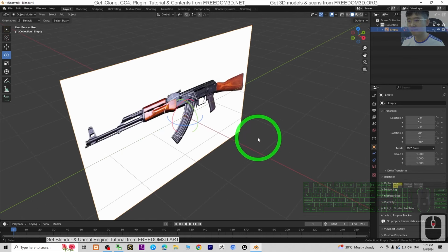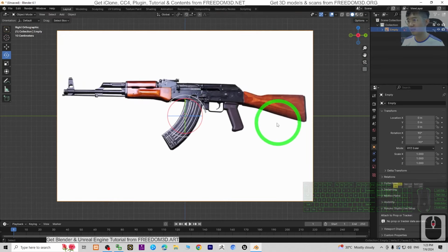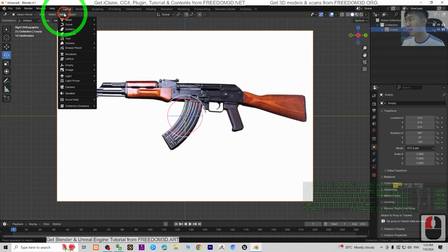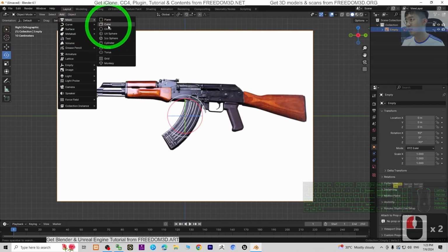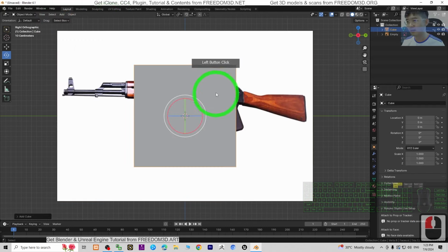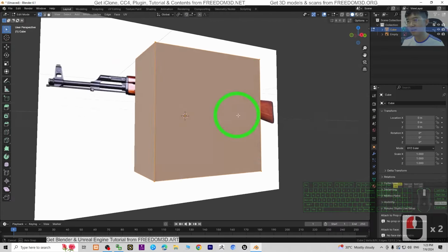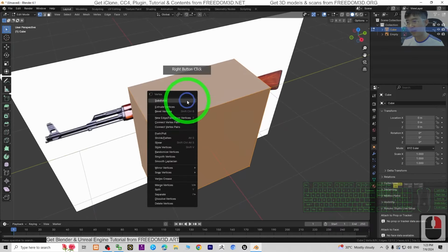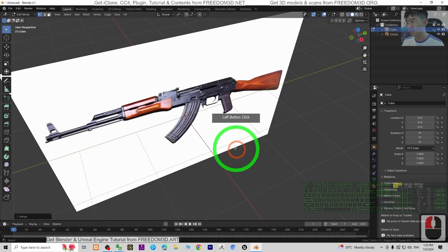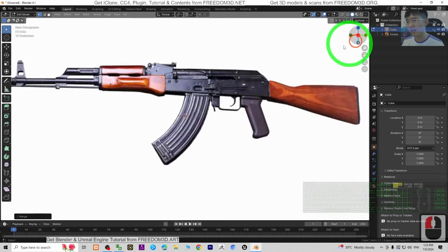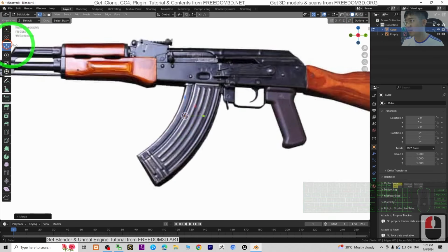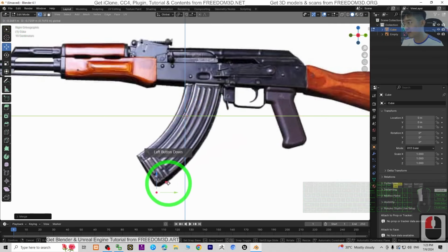So now, next, just click the X so that you can see something like this. Then add a mesh, add a cube. So go to the edit mode. You can see this is a cube. Right click it, merge vertices at the center. Now click the X. Actually it is a point. You can just drag and drop the point. Let's say I drag it to here.